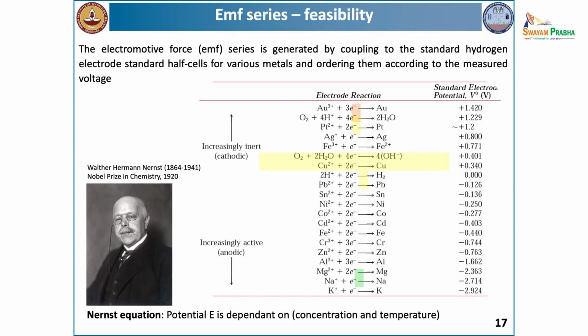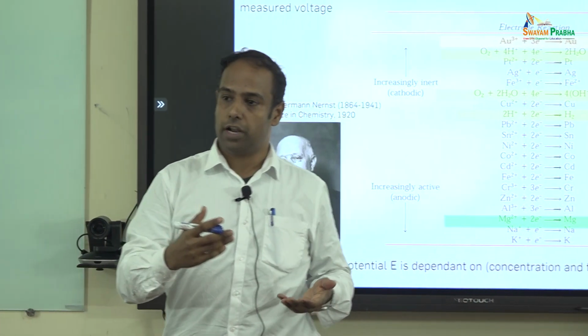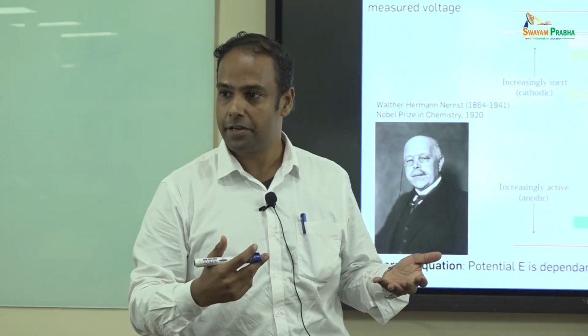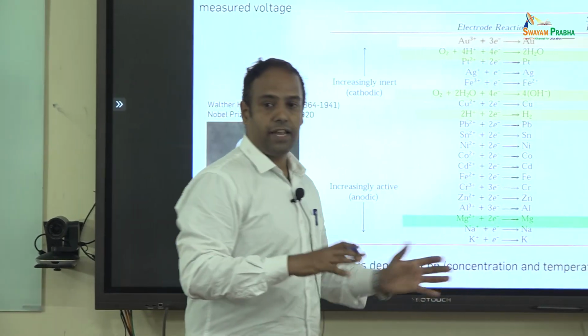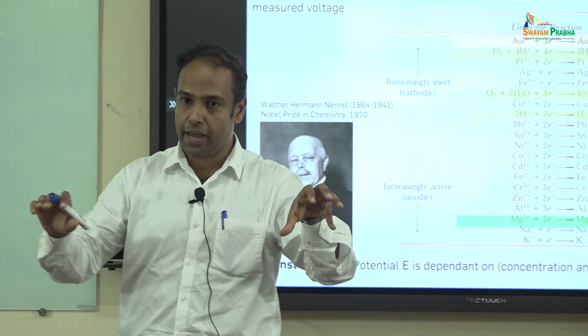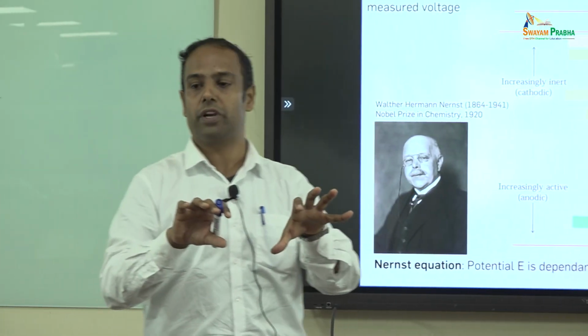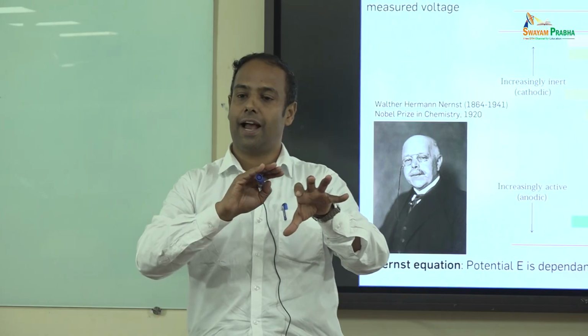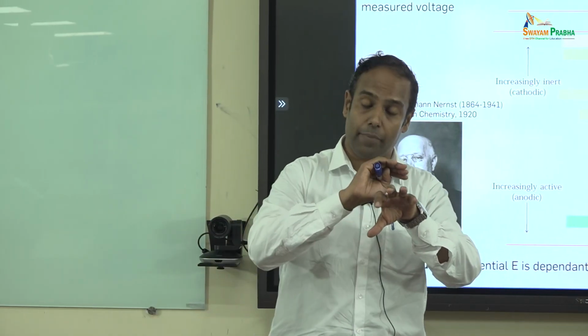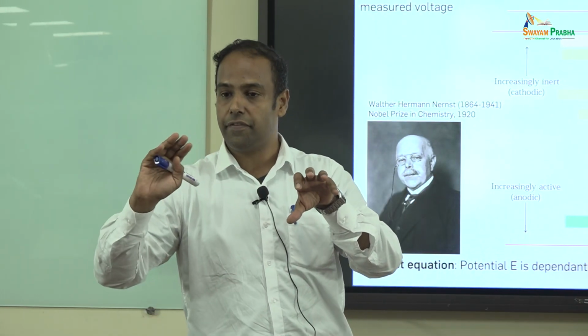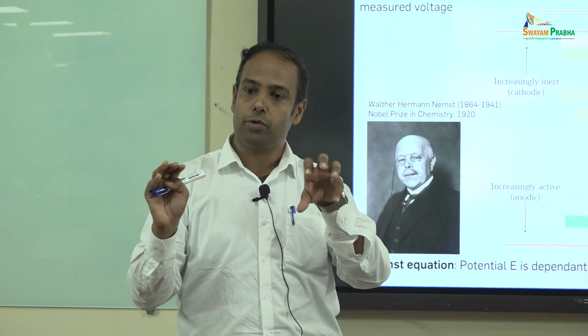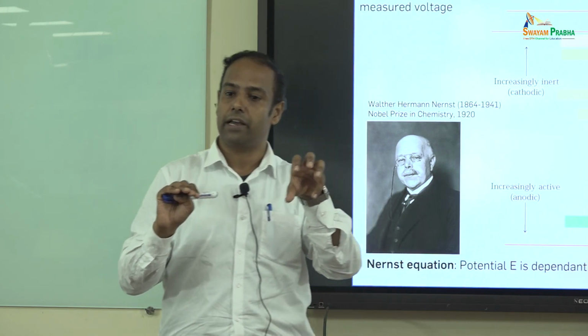Iron is saved. So, when zinc gets involved in the reaction, what happens? How is iron saved? Iron lattice cathode. So basically, if I consider a GI pipe, a galvanized iron pipe exposed to an environment, I have shifted the anodic reaction of the surface from the iron surface to zinc, and the cathodic reaction is going to happen on the iron surface.